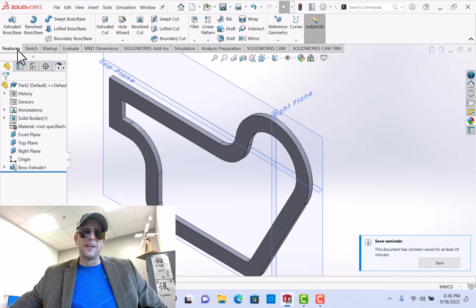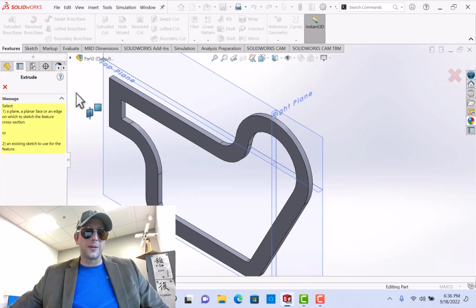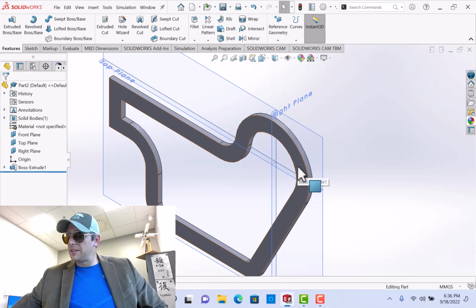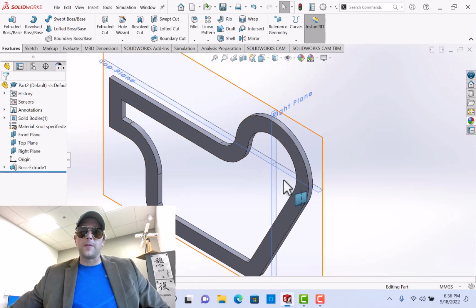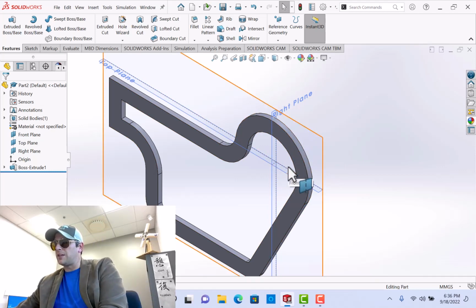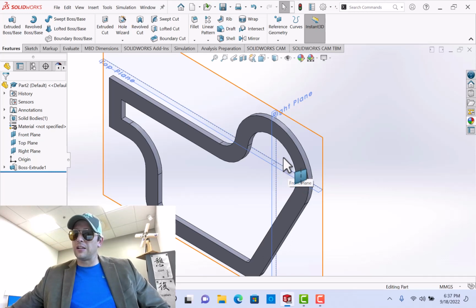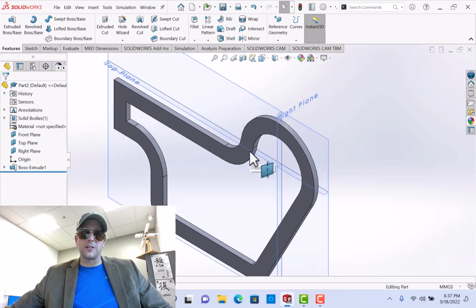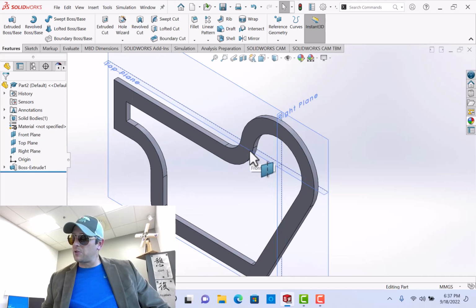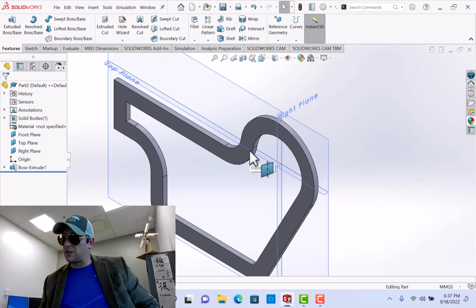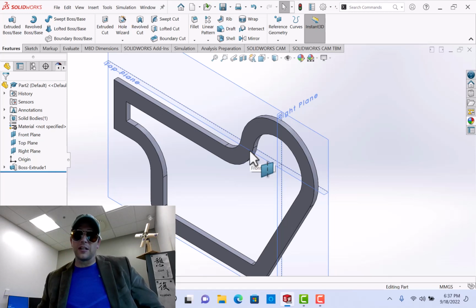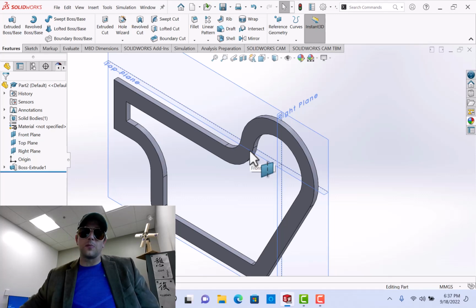it, cut through it, which is funny because I don't remember ever telling it to do an extrude cut. So I'm like, okay, well, that's nice that it did that. But it did that automatically because the sketch itself is actually within the sketch plane, and you're going back to define the sketch, and when you hit OK, it automatically does that extrude cut. So you don't have to do it in 2 separate cuts, because it had already defined it in the sketch plane, and then when it was redefined, it was defined in that same way.